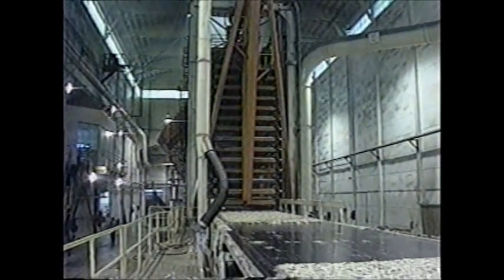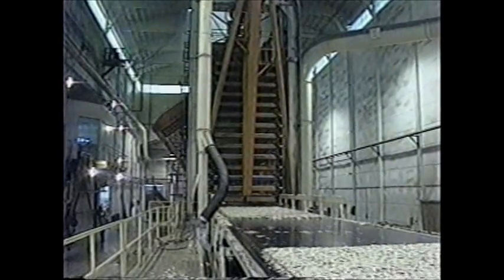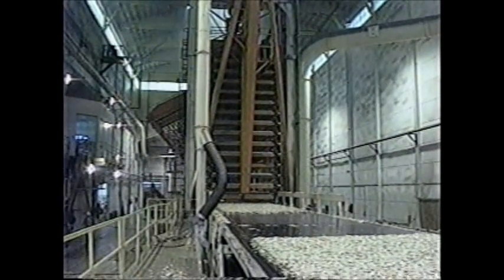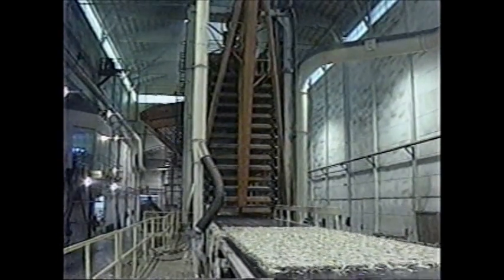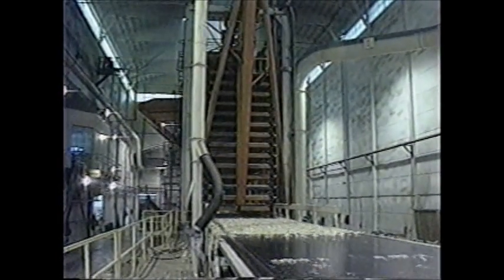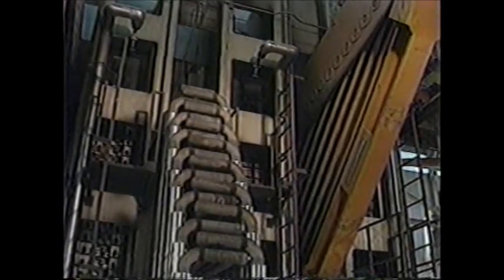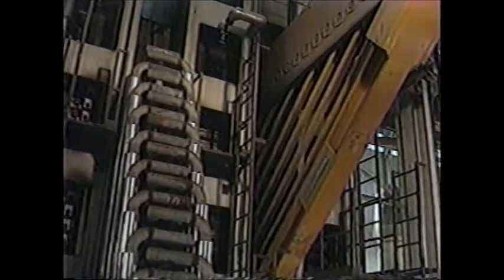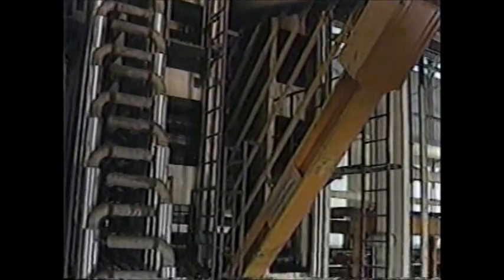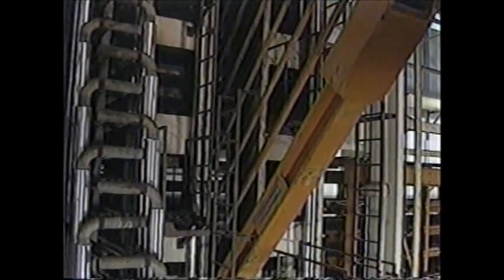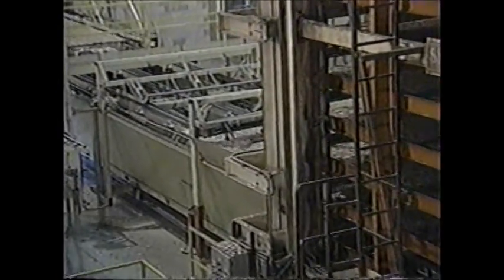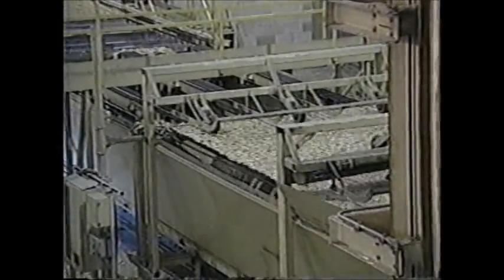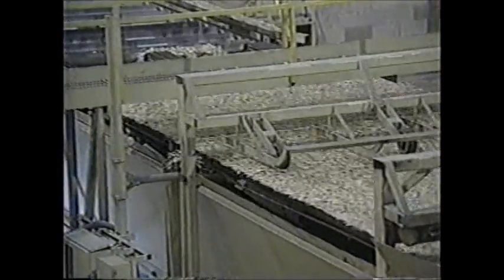The mat, after forming, is about 2 inches thick. After 3.5 to 4 minutes in the hot press, they are compressed to 3/4 of an inch. The press opens after the curing cycle, the newly formed mats are inserted, and the cured mats are removed. The cycle then continues and repeats. The cured mats are then removed from the tray system one at a time and proceed to a set of saws.